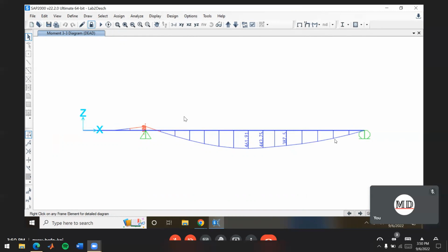Okay, I'll just note real quick, if you're plotting this out by hand as well, you might notice, hey, wait a minute, this moment diagram's flipped upside down from how we were taught to do it. That's because people have different conventions for drawing moment diagrams, and it's really confusing. I like our way better, but it is what it is. This is more of the international or European style of doing it. They flip the moment diagram so that it matches the curvature of the deflection a little better. There are benefits to it, but then you're introducing signs in your integration to get these diagrams.